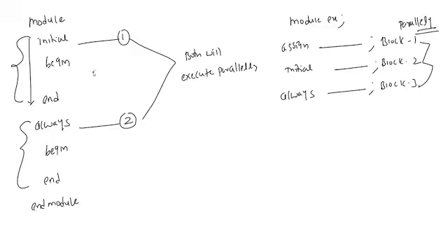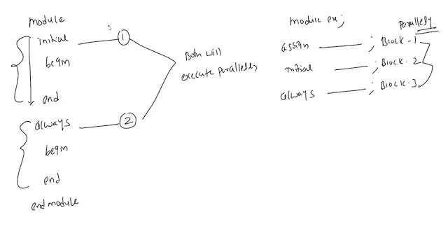All blocks will execute parallel. Then you can ask what is sequential. Did you understand? Either it may be an initial block or an always block, or an assign continuous assignment statement, when you write them within the module, all will execute parallelly. So then what is sequential, sir?